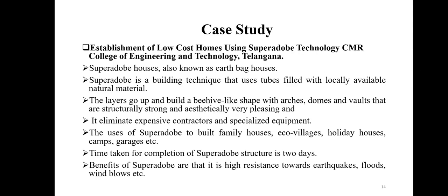Case study. Establishment of low cost homes using Superadobe Technology, CMR College of Engineering and Technology, Telangana. In this study, they conclude that this technology is known as earthbag construction. In this technology, tubes are filled with locally available material. This technology eliminates the heavy equipment needed to construct the house.